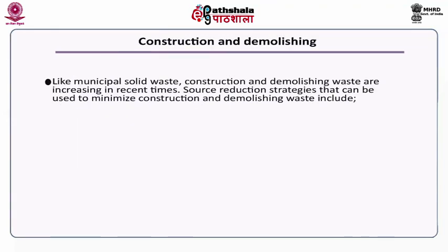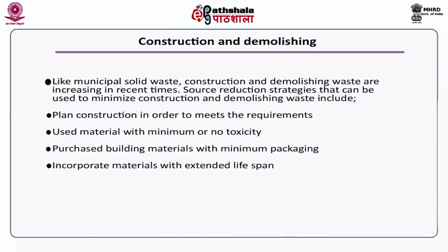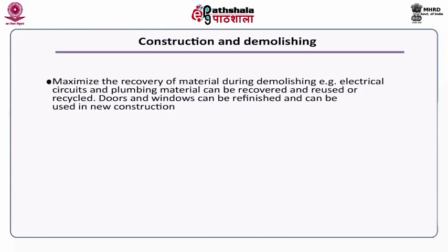Now, let us discuss some of the source reduction strategies in a construction and demolition site. Like any other municipal solid waste, construction and demolition waste are increasing in recent times. Some of the source reduction strategies can be: you can minimize the construction and demolition waste by planning a construction in order to meet the requirement, then use those materials with minimum or no toxicity. You can purchase building materials with minimum packaging material and incorporate those materials which have extended lifespan. Also you can use reusable products. So, maximize the recovery of material during demolition.